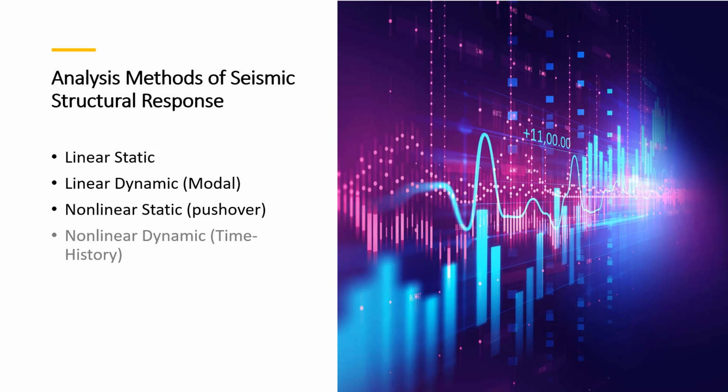The analysis methods we know for seismic assessment of structural response of buildings are different. Normally codes, design codes or standards, include linear static and dynamic modal methods, and nonlinear static analysis methods, which are considered the state of the art of the seismic assessment of existing structures.